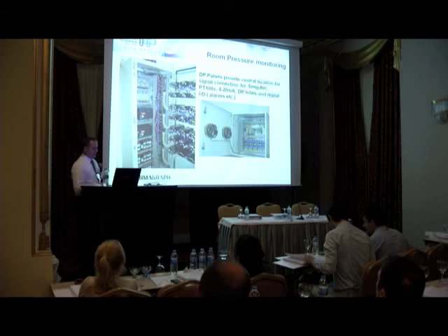We've talked about alarms. The operator can acknowledge alarms and put a comment in. That's done by clicking here on the alarm. You get a little drop box come up and you can acknowledge alarms either for multiple transitions or single transitions. And there is an option to have a standing comment put in there, or you can put a freeform comment. So something might be, we've got an alarm, we've taken the sensor out for calibration.